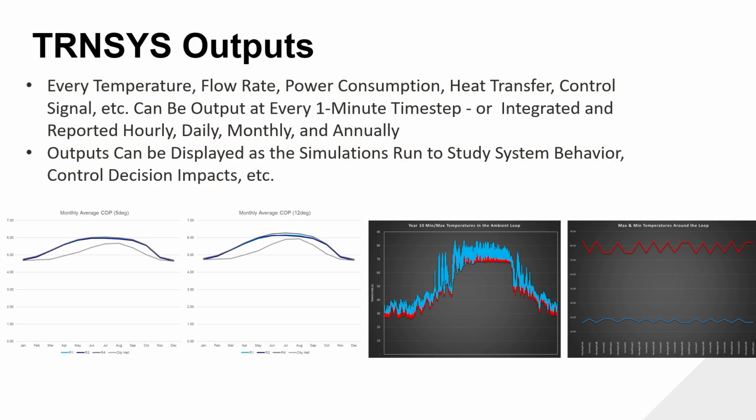Are you actually able to use certain assets at certain times of the year, or are they counterintuitive to the other asset? Right? Like the river might be 80 degrees in the middle of summer, my bore field might only be 70. Why would I run the river system if my bore field is colder, giving better efficiency? So you have to really understand all of those things and be able to put them together in a system, look at it holistically and how it all interacts.